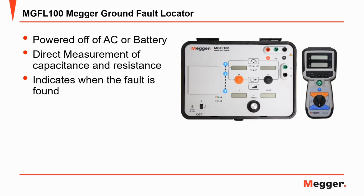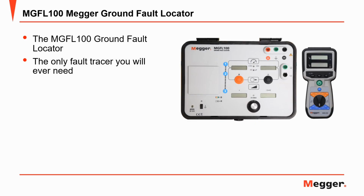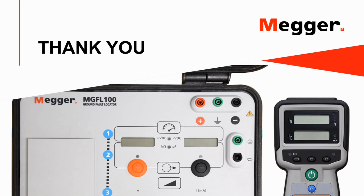Alarms indicate when the fault is found. The instrument tells you when you're on the line with the real fault. Programmable limits. Program the unit with your maximum voltage and current limits. Never trip a breaker again. Detects faults up to 400 k-ohm on systems up to 600 volts. Locate both low impedance faults and high impedance faults due to water ingress on both AC and DC systems. The MGFL100, it is the only fault tracer you will ever need.